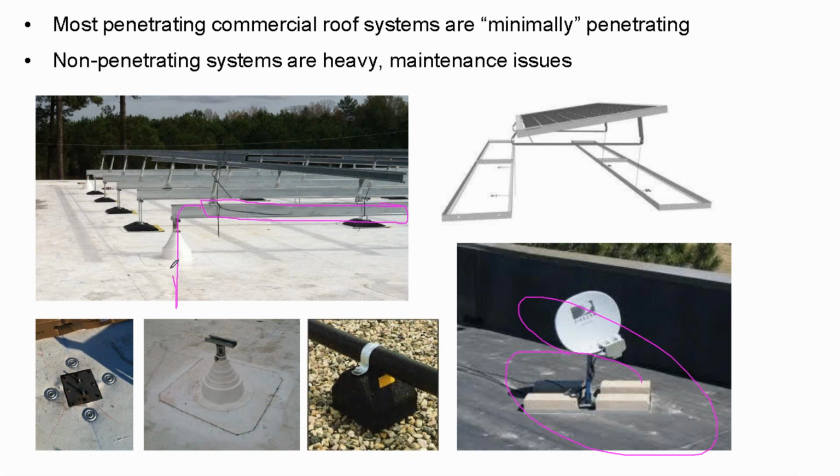I like going into the roof with my home run cables, but if you're running your conduit across the roof, as is common, often you'll get copper cable inside aluminum conduit at the hottest part of the building.